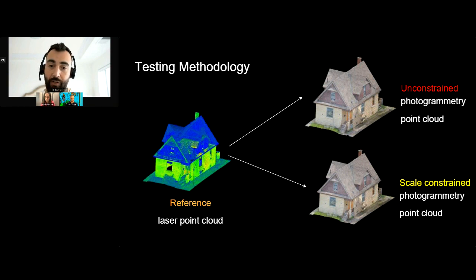And then we're going to do two different versions of the photogrammetry point cloud. The first version is unconstrained, meaning no controls. Really, the only thing that was there is what the software was able to find in the images and match, and also those stickers that I placed around the surface, and those help align everything. This asset actually didn't really need those stickers, but I put them in there because it really helps bring the laser scan and the photogrammetry data together in post-processing.